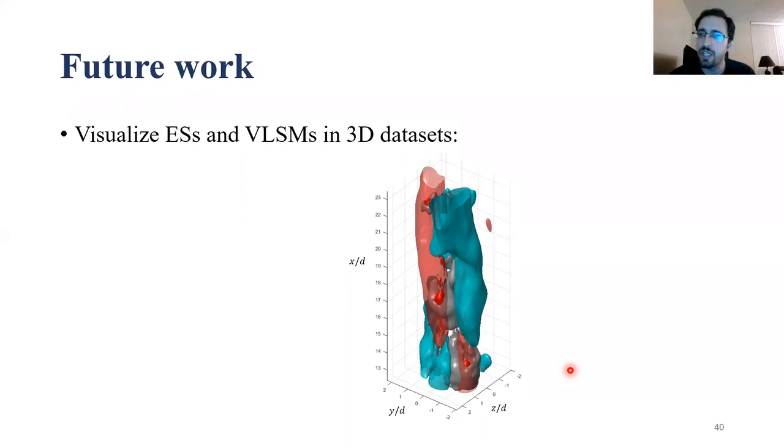So the location that we conducted the measurements at was quite far away from the jet exit. In my experience, I doubt that we had a lot of oscillations in the non-turbulent region around there for the center line to be oscillating. And the other thing is that the Reynolds number is quite high, 50,000. So the jet is quite turbulent, and I doubt that the center line could be oscillating, to be honest.